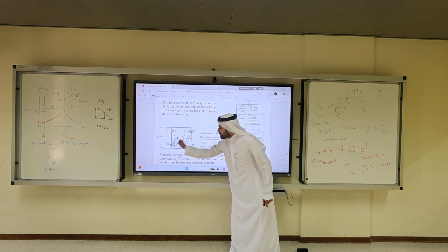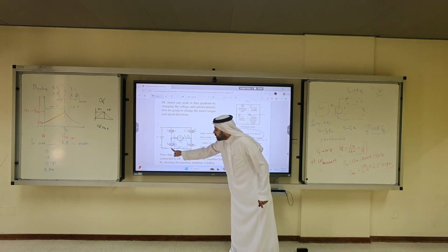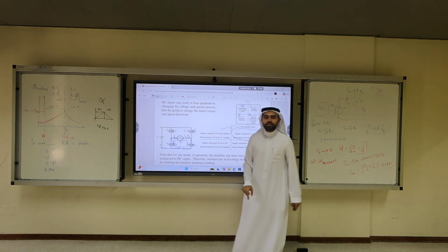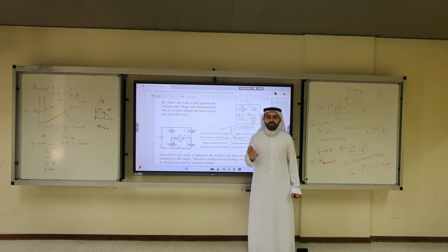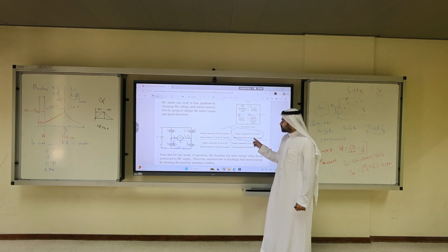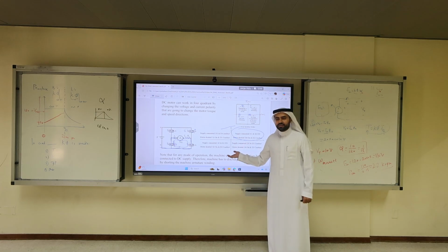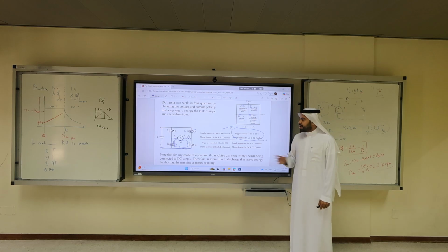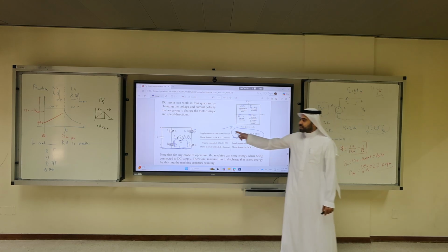So if I want to control the speed, what will happen? During the off moments, do I send pulses to S2? No, I don't send pulses to S2. I make this off. This voltage will be naturally higher, then diode 2 will be on. The diode, can you control the diode? No. By itself it will be on. So the formula sheet, you can have this figure in the exam. Okay? Next lecture we will continue the other three quadrants.